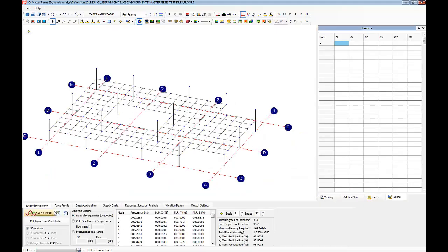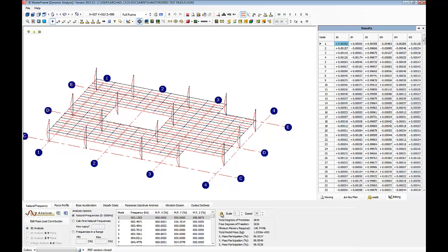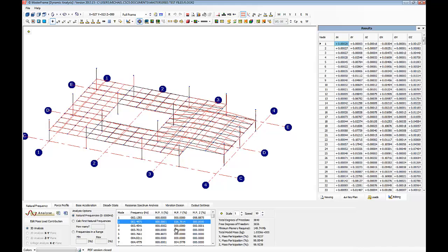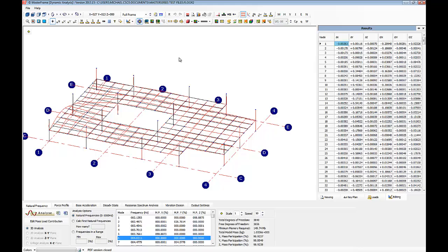And first thing, again, it always comes into the modal analysis, and again this one already has a modal analysis performed, so you can tell that by the mode shapes here, and we can look at the modes. First one here is actually a lateral sort of mode shape, so it won't really be of concern to us in the response factor, which is more concerned with vertical vibrations. The second one will be definitely of interest, and these sort of ones here as well. They're all vertical mode shapes.